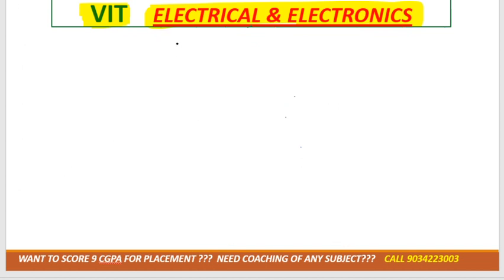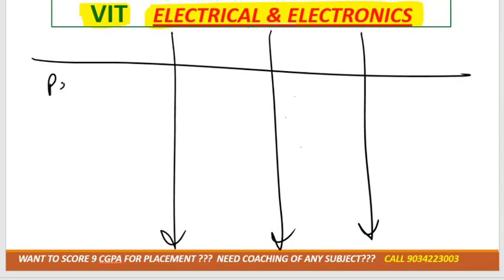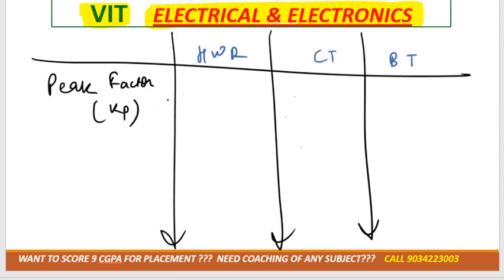Now the next formula: similarly they can ask you the peak factor. Peak factor is denoted by Kp, for HWR, for center tap, and for bridge type. Kp formula is Vmax divided by Vrms.